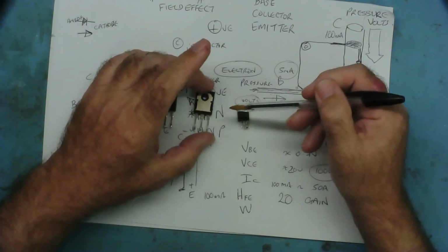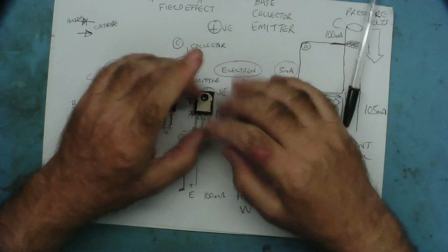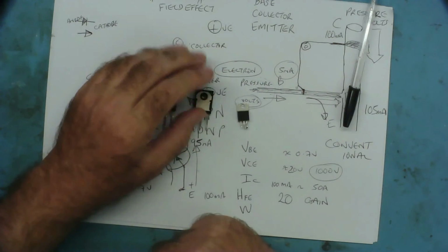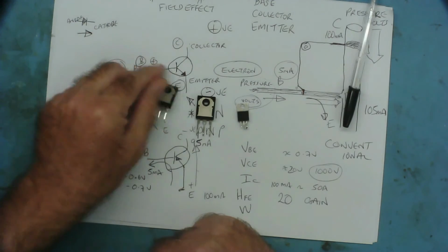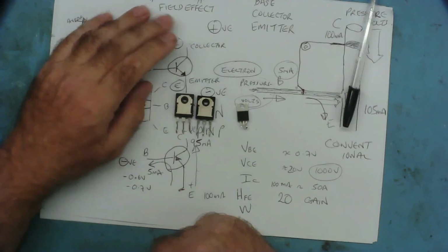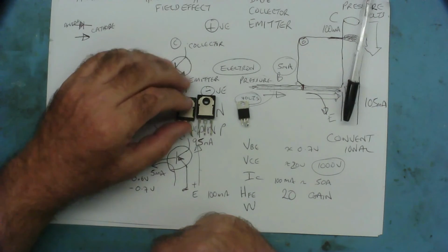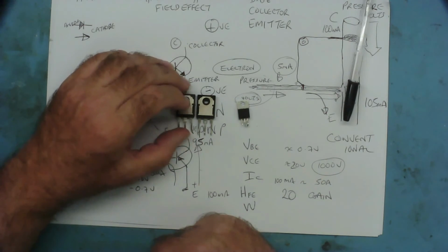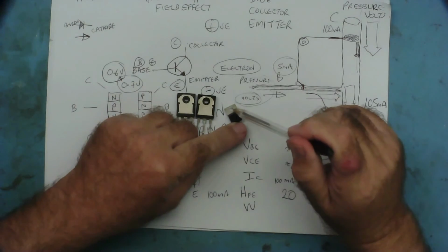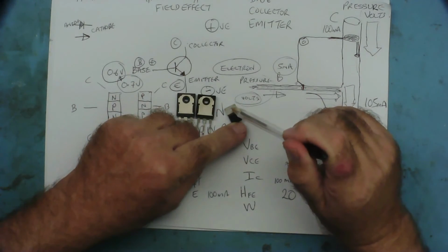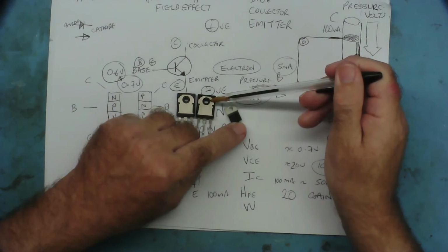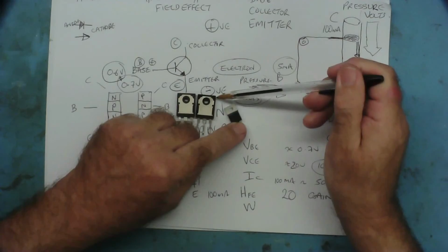Often behind these, you will find a washer, a square washer, sometimes made of a clear material called mica, which is basically a mineral, and sometimes a rubbery, grey, thermal type pad as well, which you'll find these days. With ones like this one, you'll often find the bolt that goes through has a little plastic insert that sits inside the hole, effectively insulating the bolt from the metal tab.